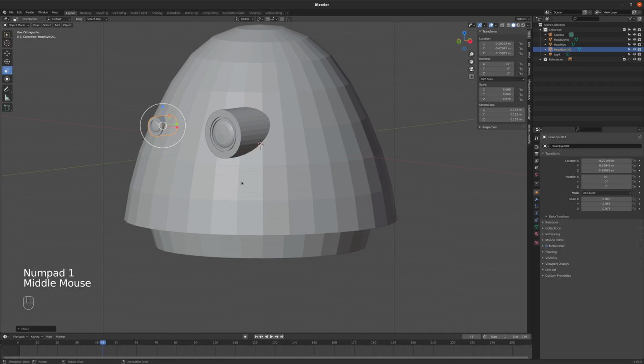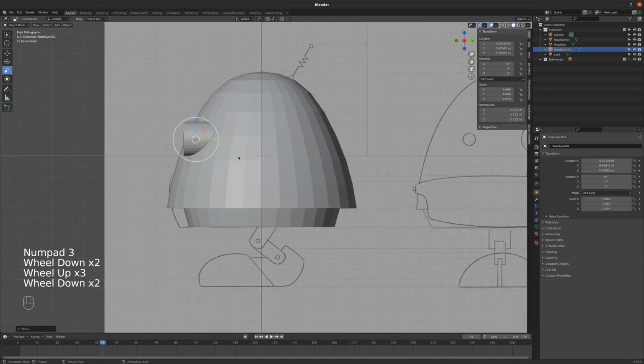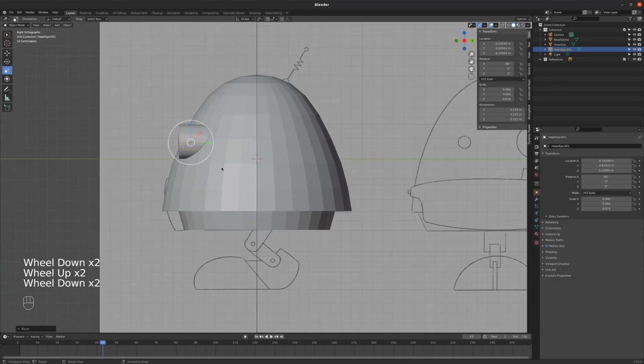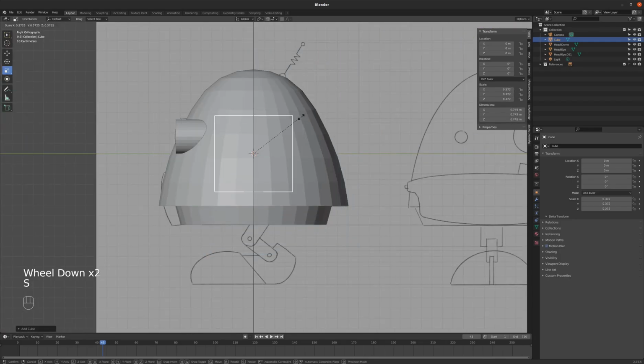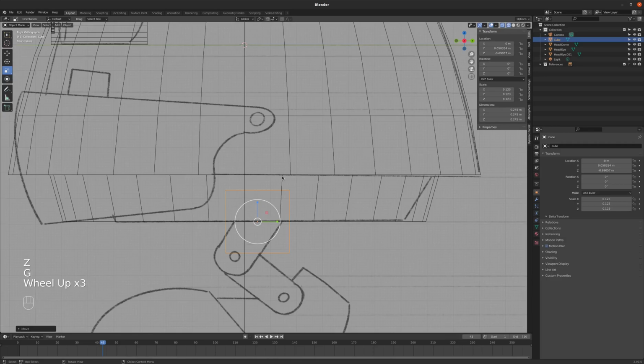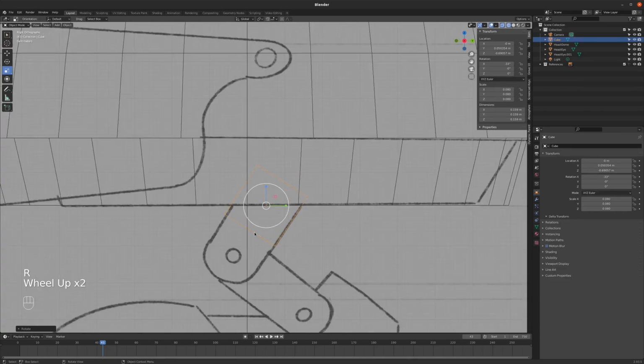So let's see, we're several minutes into this tutorial right now. I don't know if I'm going to be able to give this enough time to actually finish it, but we'll see what we can do fast. So I'm going to box model these leg pieces. We'll create a cube. Rotate that and scale it. And I now need to scale this a little bit more. So I'm going to scale it along its original z-axis, which is now at a tilt. So S double Z will select that original axis. G, Z, Z will also tilt it along that original axis. So that's a handy trick.